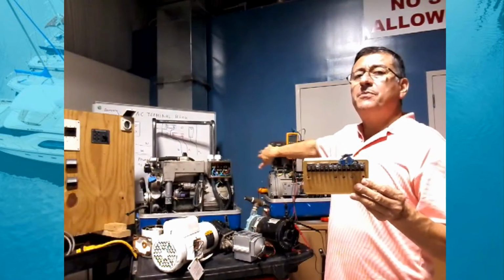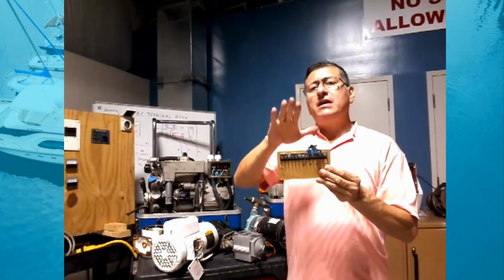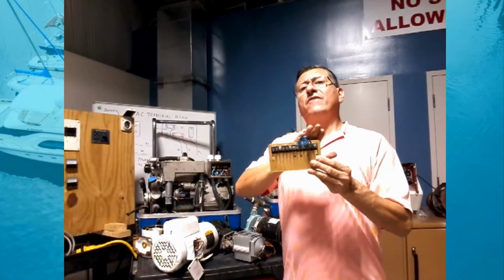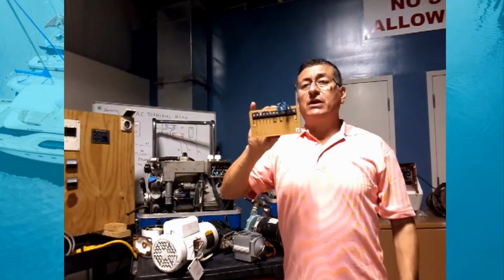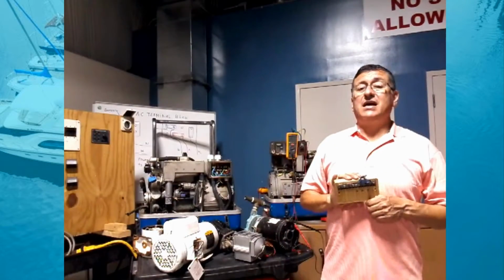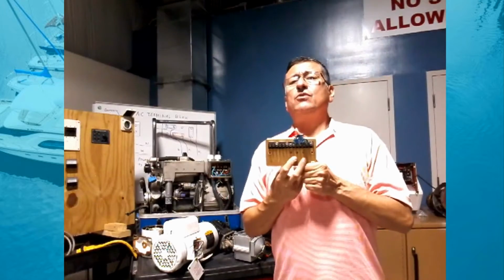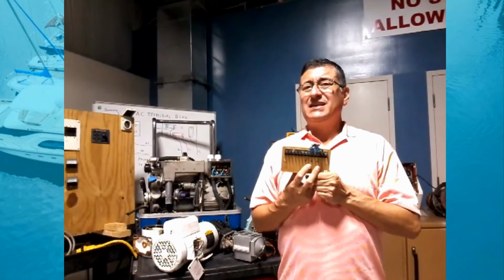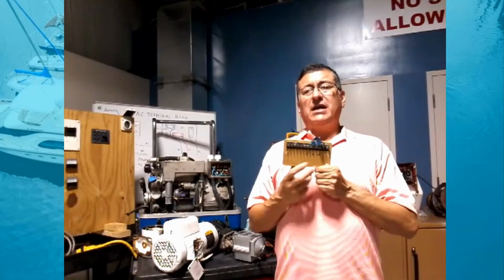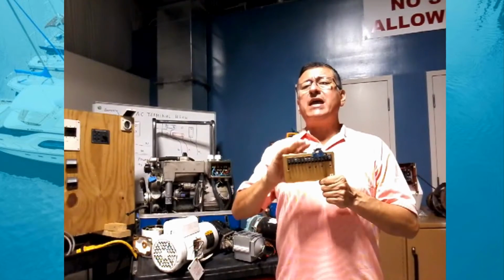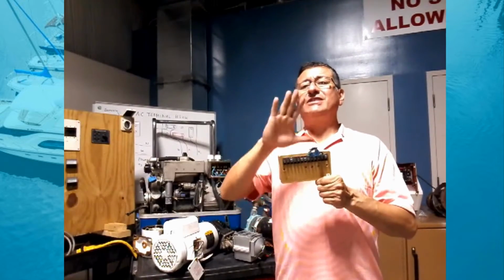It's basically RPMs on the engine. Never try to fix frequency problems with the voltage regulator. There are a couple of manufacturers that put frequency on one of those spots, but it's not common. I am going to explain later how you fix the voltage here.